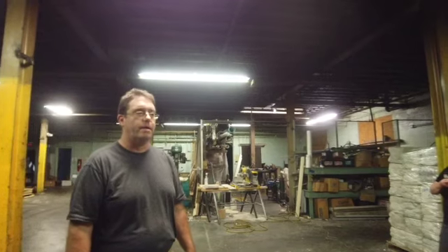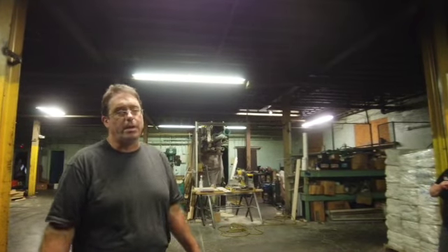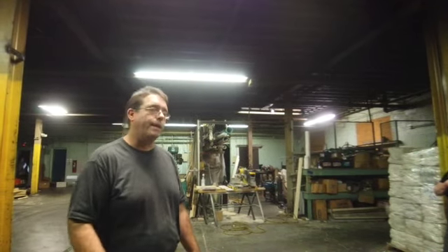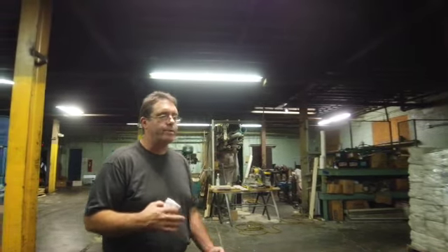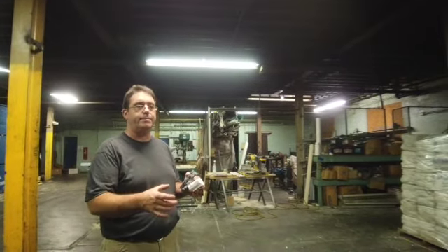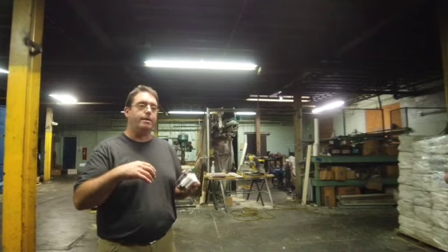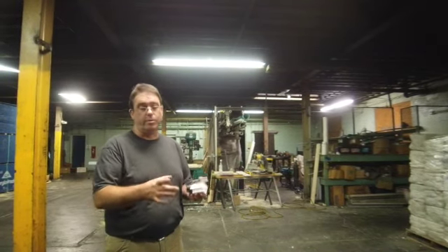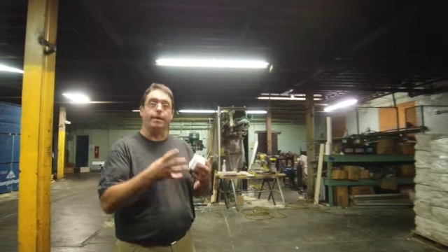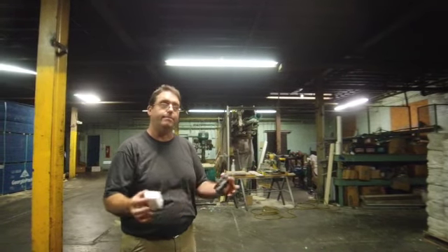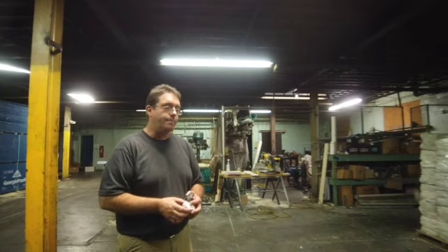Structurally, the panels are what we would call curtain wall panels, so they don't actually have any structural integrity. They can be incorporated into a structural system, whether it's double dimensional 2x at the seams of each panel, and then it's almost like you're building these panels around either a timber frame or some other steel structure or inset lumber that is the structural skeleton, and then the panel just encases it.